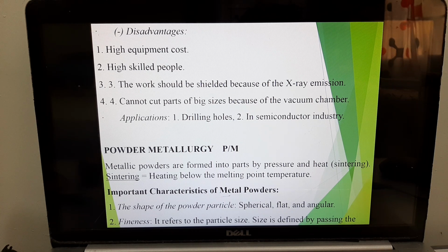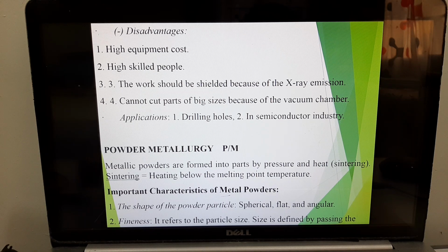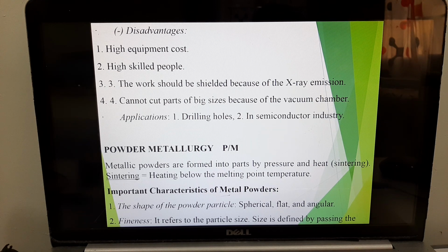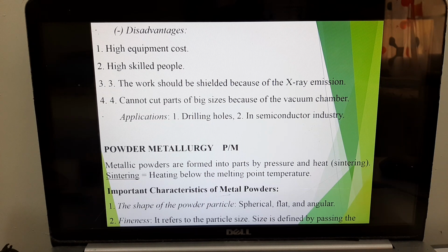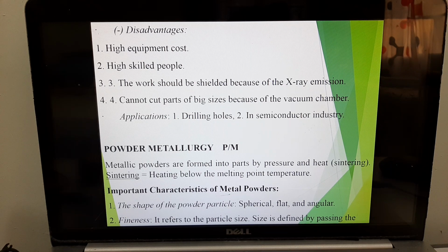Therefore, electron beam needs to be performed in a vacuum chamber. So when you're doing electron beam machining, your object and your process need to be conducted in a vacuum environment, and creating a vacuum environment is very costly. Therefore, we would consider electron beam machining carefully, though it gives you the same results, because it's a more costly affair, as we are doing it in a vacuum chamber.